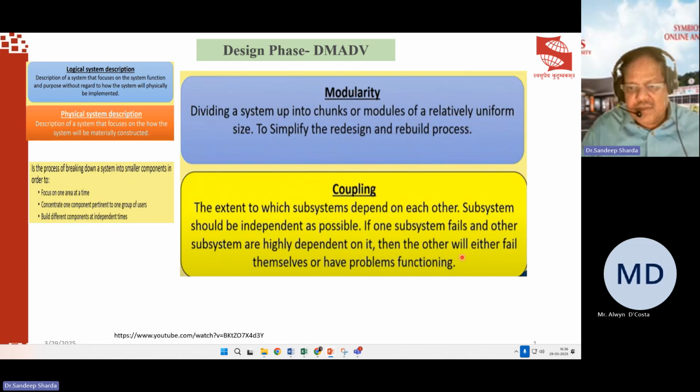Prior to any damage to the shaft and the other components of the motor and pump, the coupling's rubber or flexible pads start getting damaged. So these are very less costly parts to replace. In the design phase, we consider how the coupling can be designed in such a way that it reduces that type of failure.